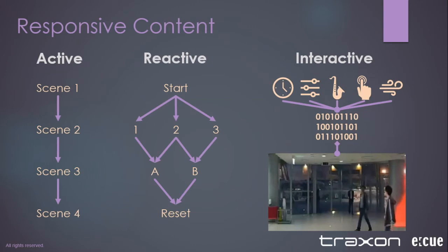So we break dynamic lighting typically out into 3 tiers of control complexity. We have the active, reactive, and interactive. Active is dynamic scenes, but they're pre-baked scenes, and they're either just run through in a timeline sequence or based on open, close, cleaning mode, and special event. That's it.